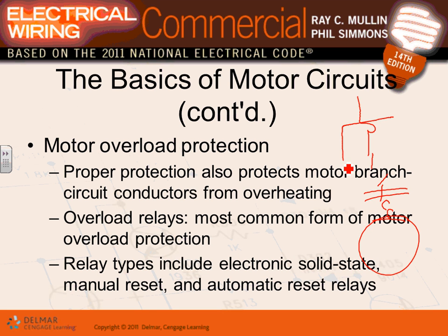If you look at this, this is a typical controller for a motor. You start with your disconnect, the power comes in. You have your overcurrent protection here, then the controller and the overload protection device right underneath it, and the controller right into it. That's exactly what they do for any motor. They can either put them in a box, that's called a combo starter, or you can put them in a panel, that's called an MCC.